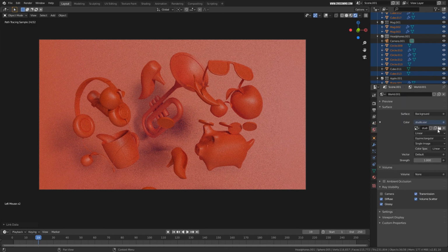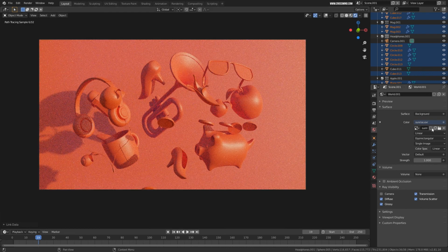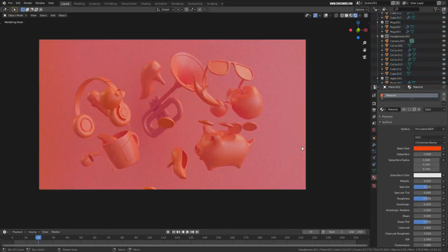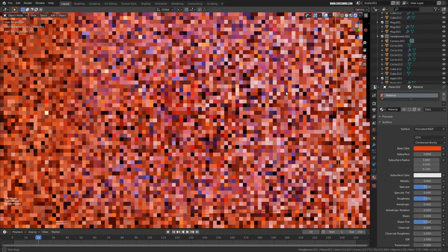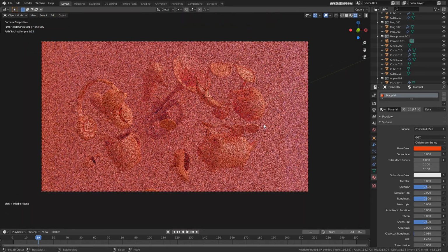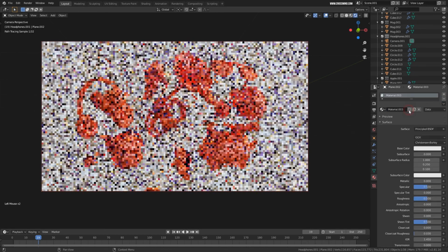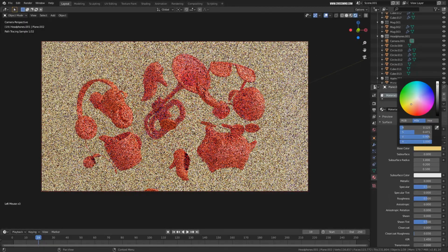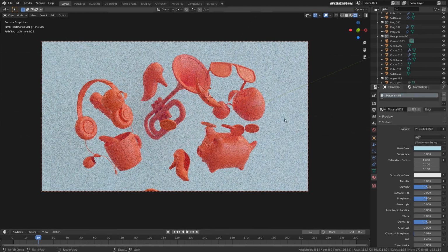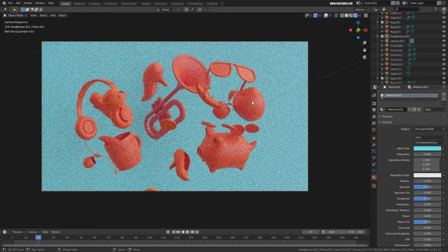Now if you want, you can experiment more with the HDR. Maybe bring in a nice hard shadow over here, or maybe an interior HDR. Or what you can do is select the background panel which we have over here, and press 0 to go back to camera view. Now I'll select this background panel, delete the material and bring a new one, so that I can create some contrast. Just play with the color settings, choose your favorite colors and give it a nice look, and you should be able to render a decent image with just these settings.